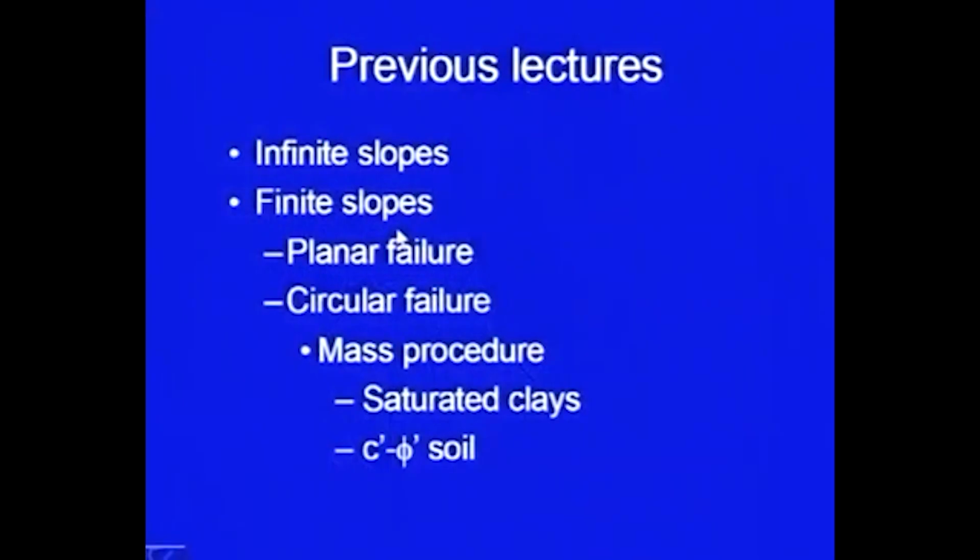After that we moved on to the finite slopes, which are smaller in extent, and there we discussed the method of planar failure, where we took the failure surface to be a plane. Then we started discussing the circular failure cases, where the failure surface is circular, a cylindrical surface.